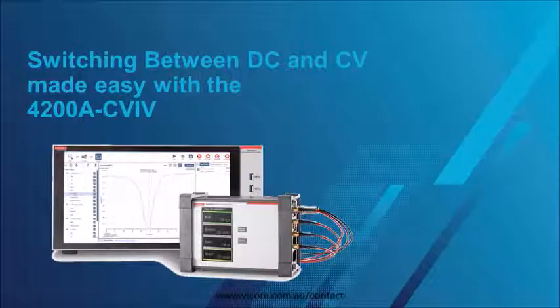You may have noticed during the last few slides that most of the tests I went through required slightly, or not so slightly, different connections to the device under test. We talked earlier about the fact that every time you rewire a test, you change cable constants ever so slightly. This then requires you to rerun any compensations to update the constants you are using, which then slows down the test and just makes for a generally painful process.